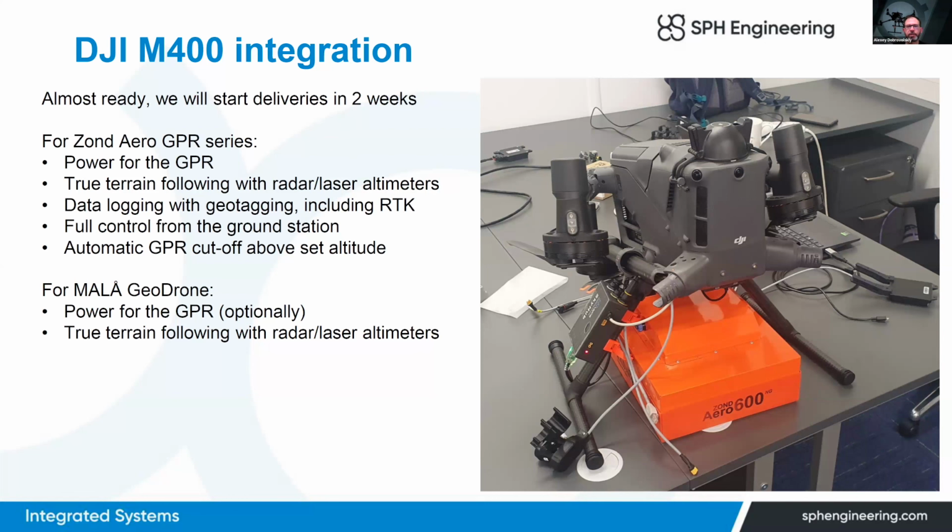It is quite important if you want to be fully compliant with the requirements of regulators. In most countries, including all European Union, including United States, including Canada, it is prohibited to carry active working GPR antenna with the elevation more than 1 meter above the surface. So drone can fly higher, for example, when it is flying to or from the survey area, but at those parts of flight, GPR should not emit anything to be fully compliant with regulations.